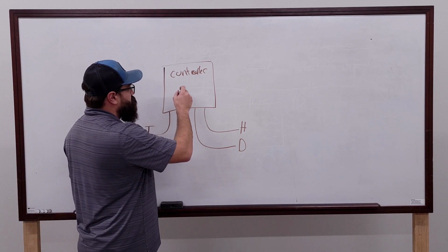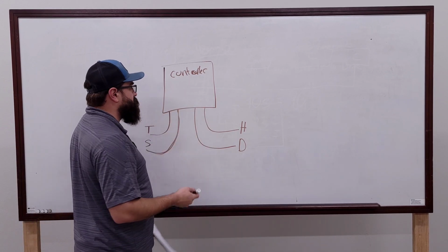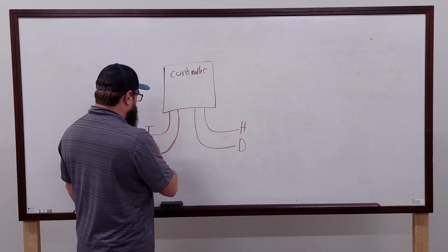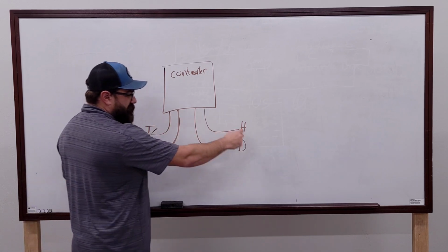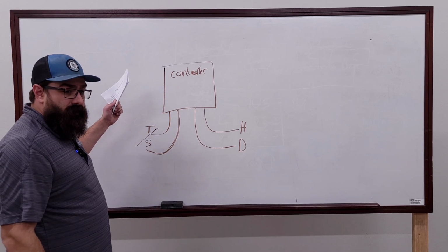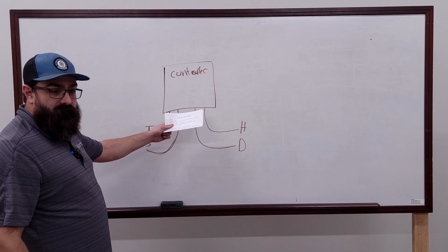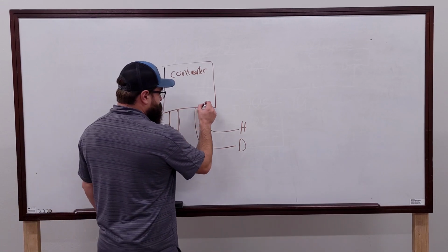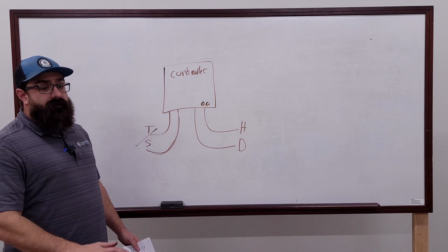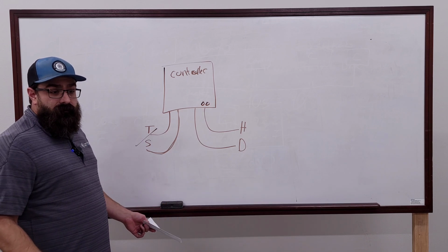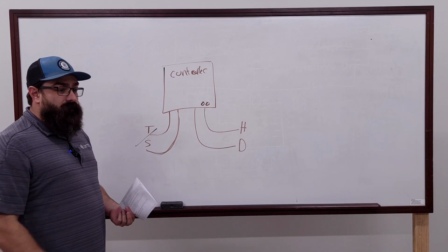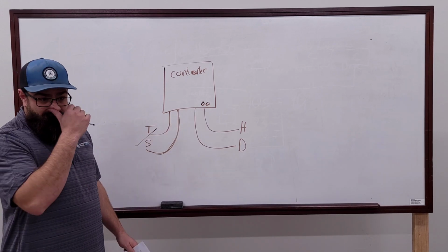As long as this controller, if it is standalone, is set up to run all the time, or if it is networked and it's given a command to be occupied, it will compare these two and determine what these outputs do. If you're looking at a front end and it's saying this is putting out 100% heat, you should be able to come to these two terminals, put a meter on them, and get a value. I don't know what that value is supposed to be. It could be a 0 to 10, it could be an on-off, it can be 0 to 5, it could be whatever, but you'll get a value at those terminals.